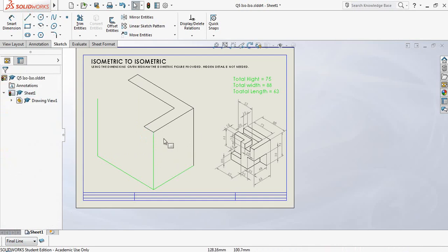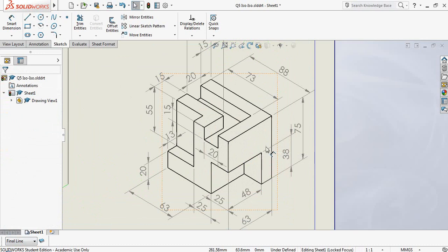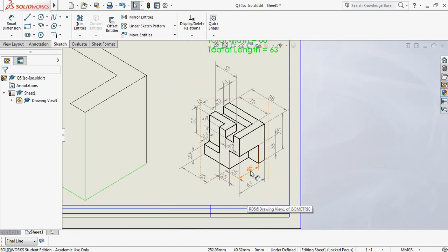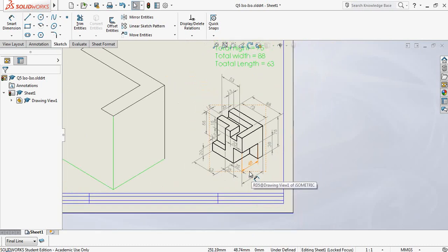If I want to cover this platform over here, or this face of my box, I simply look at this face of my box over here, and it looks like it's got an L shape to it, so I need to get that done. If I run my pencil along this line over here, this 30-degree line here, I've only got that small little line over there that's in dark. So that is obviously 48, or 63 minus 48. In this case, I'm simply going to go ahead and find what length this line is.